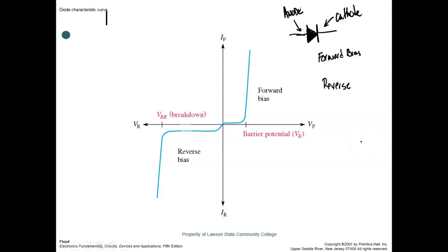Now, when we forward bias it, it acts like a closed switch, right? But it's not actually, because a closed switch would drop 0 volts. If this is silicon, then it's going to drop approximately what? Yeah, around 0.7 or 700 millivolts. And this is approximate, like I said, some books teach 600 millivolts. Our book teaches 700 millivolts. Which one's right? Both of them.